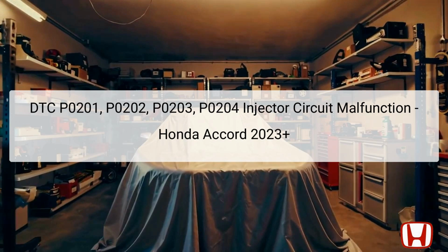Specifically, P0201 relates to the number 1 cylinder injector, P0202 to the number 2 cylinder injector, P0203 to the number 3 cylinder injector, and P0204 to the number 4 cylinder injector. These codes indicate that the engine's powertrain control module, or PCM, has detected an abnormality in the injector's operation as it relates to its command signals.